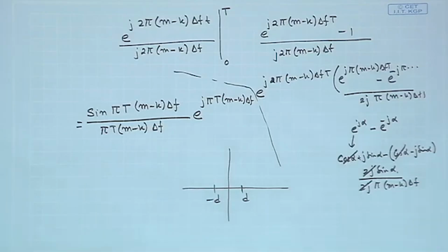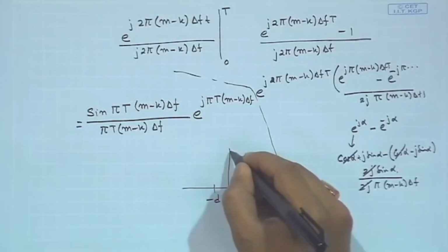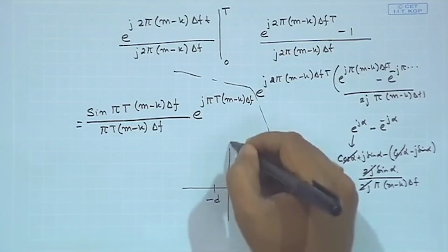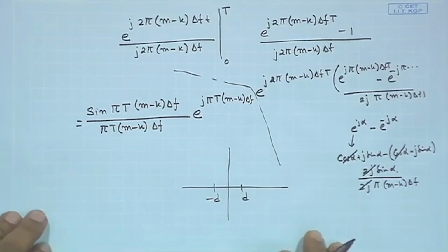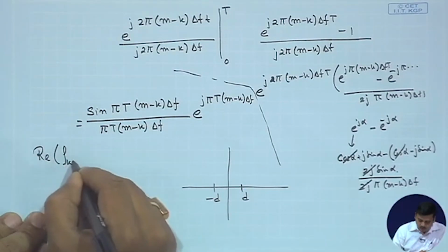So, if we are doing frequency shift keying, when we are selecting the frequency, we are choosing one of these frequencies with the presence of a signal, right. What we are interested in is the signal being present or not, and not further details of it, and in any case this does not have a Q component. So, we can be interested in the real part of rho k m.